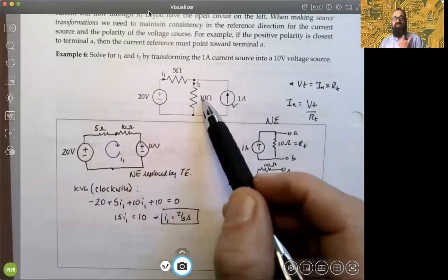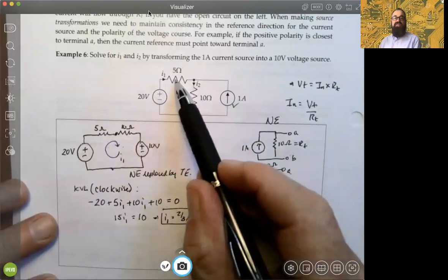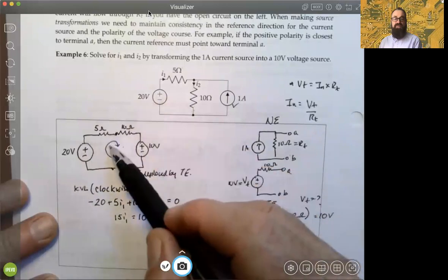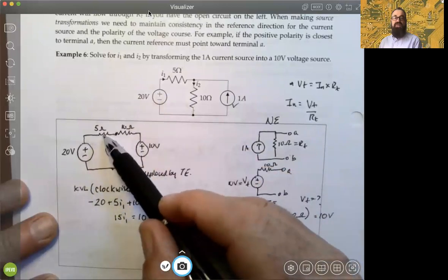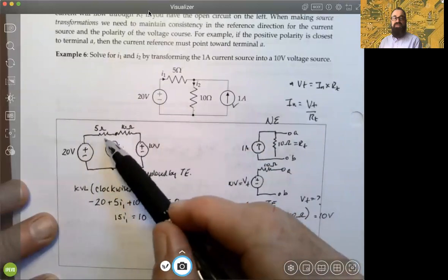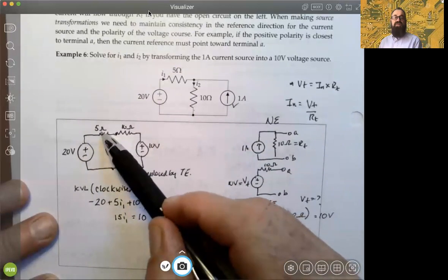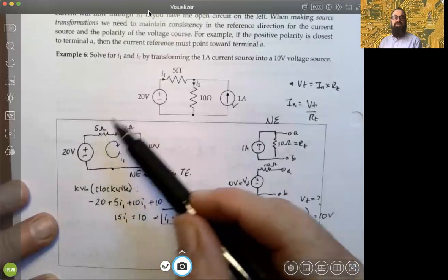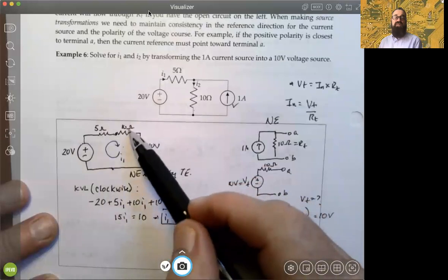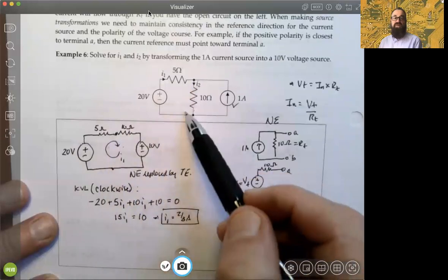No, this is a different current, but this situation here is equivalent. In other words, we have found out from this voltage source the mesh currents flowing inside here. This is the current through the 5 ohm resistance, which is the same 5 ohm resistance here, right? This is in series, and these two are not in series here.